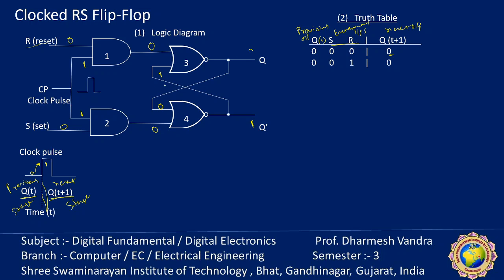The Q is equal to 0. Reset is changed to 1. So 1, 1, this will become changed to 1. 1, 1, 0, 0, 0, 1. This is not changed. The output of gate number 2 is, with S equal to 0 and reset equal to 1, the third combination 0 1 0. Let me first clear everything.